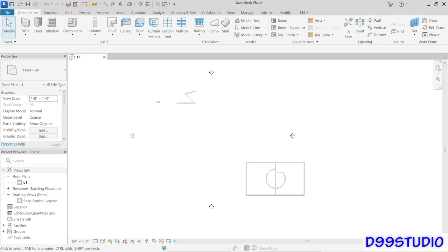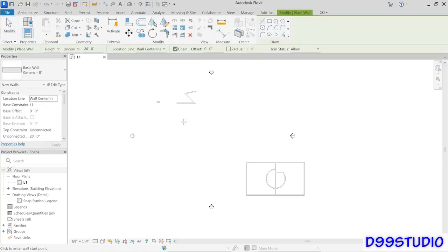Now, the last thing I want to talk about with increment snaps is if I start here and I'm moving along, you can see that it's giving me the fixed increments. Notice what happened though when it senses other geometry. It will always try to snap to other geometry. And notice that it just goes down to this really fine fractional increment the minute I did that, right? So if I come over here a little further, go back right there, it goes really fine and then really fine, or the same thing over here, really fine.